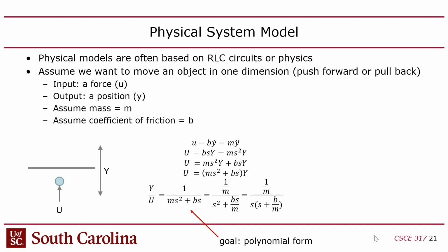That's the friction, right? It's going to take out B, which is the coefficient of friction. But friction is scaled according to the speed that you're moving across it. So y is the position, and y dot, this notation, just means the first derivative of y, the position. The first derivative of the position is the velocity, so you multiply that by the coefficient of friction. Then that gets subtracted from the force that you're pushing into the coin, right?